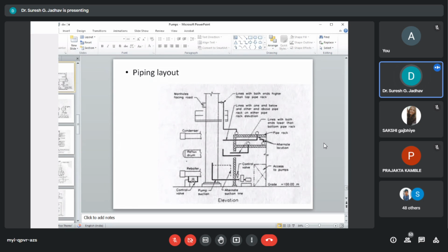For economic and easy support, piping should drop immediately upon leaving the tower nozzle and run parallel and as close to the tower as possible. The insulation thickness of the tower and that of any possible flange on the tower as well as the line should be considered while deciding the distance. The vertical line can be a suitable location for a straight run of an orifice.